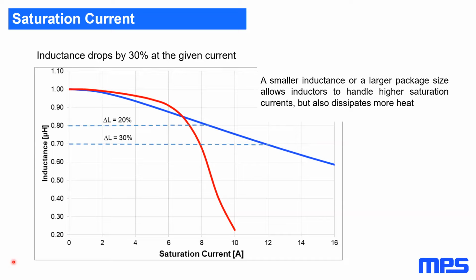But if you want to know in detail how these ACR losses, these copper losses, behave, you can search in Google. There are some charts that describe at what frequency these losses, the proximity and skin effect, are increasing. They are very low at lower frequencies, but they get larger with increasing frequency. But it's something you cannot read in the datasheet. You can just see on the charts to get an idea in what direction it is going.